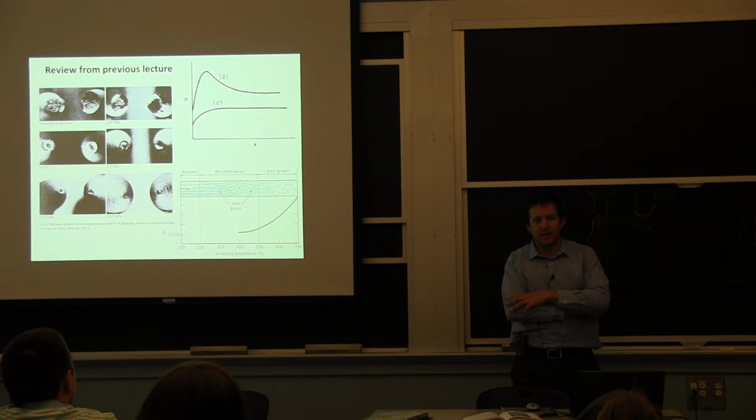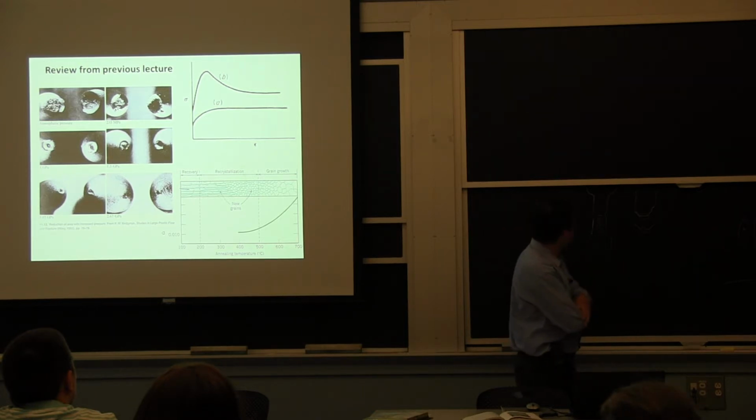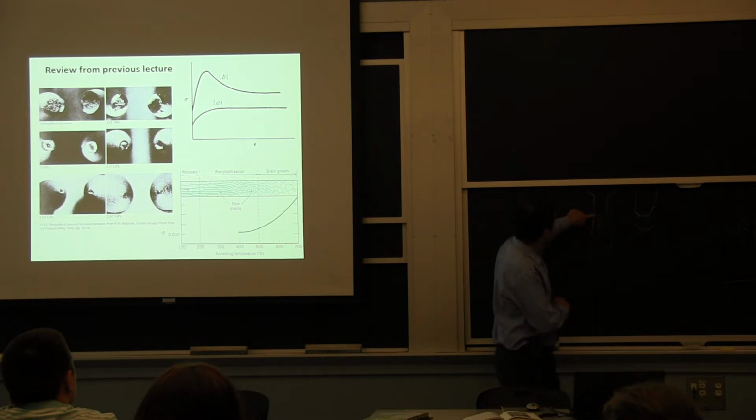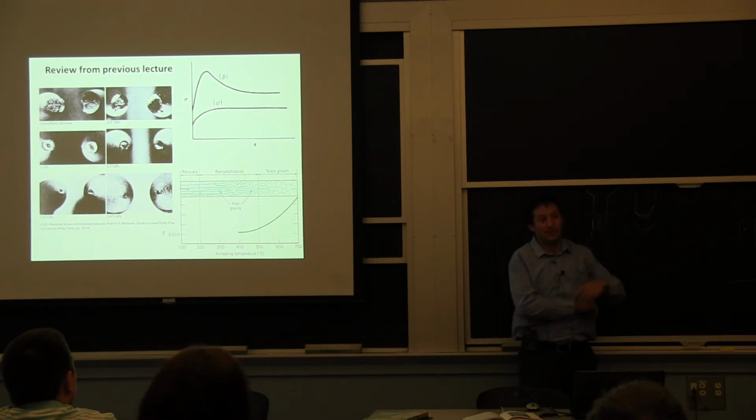So it's just another demonstration that what we get out of the tensile test at some point starts not having anything to do with the hardening of the material, with how exactly things are happening in it. So even when we form that neck here, there'll be a point where even if we were to monitor the exact net area of that section, we still don't take into account that we're forming voids in it.